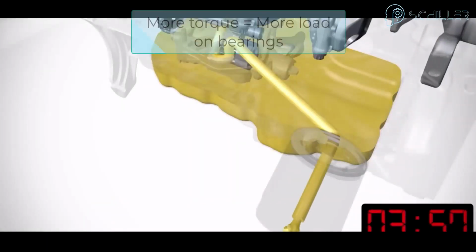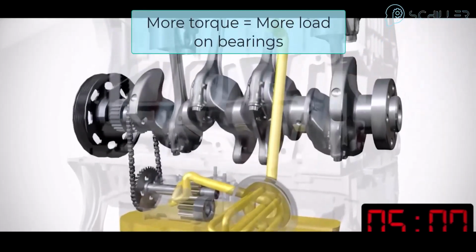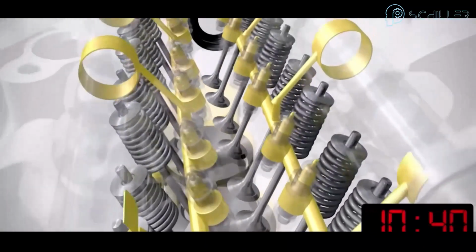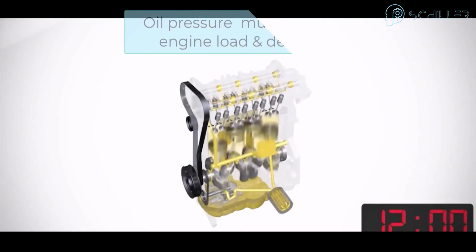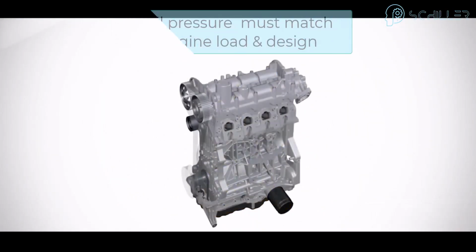When engine torque and power are increased, the bearings and crankshaft face significantly higher loads. To prevent metal-to-metal contact and preserve the critical hydrodynamic oil film, it's essential to raise system pressure slightly. Without this adjustment, the engine risks premature wear or even serious damage during dynamometer testing and heavy use. Oil pressure should match both engine load and the engine's mechanical design.